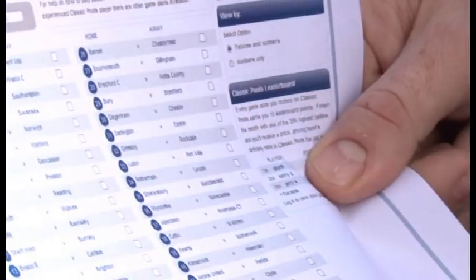We've seen that the schedule of inspection is quite an in-depth subject, which, although arranged into a neat checkbox style list, is not a checklist which the inspector can work through sequentially. Although it looks like the football pools, it's not just any random 8 from 10. You've got to take extreme care with your entry. And when you're actually inspecting, you'll be cross-referencing between sections all the time. And in some cases, your inspection will be focusing on a number of the boxes at the same time.